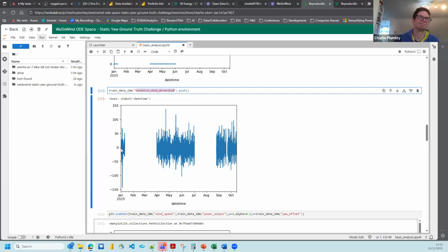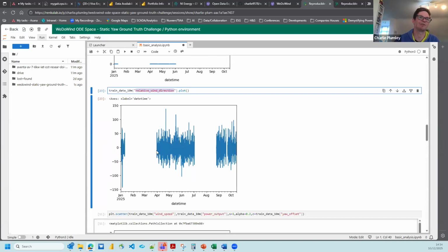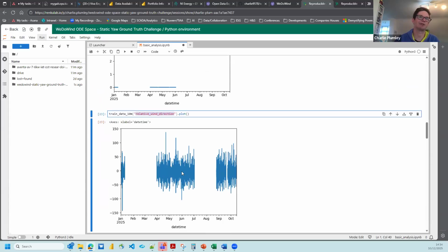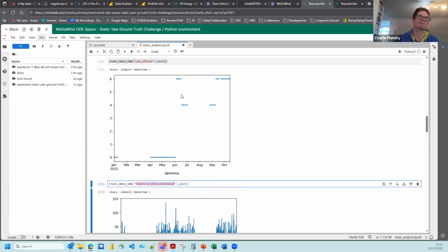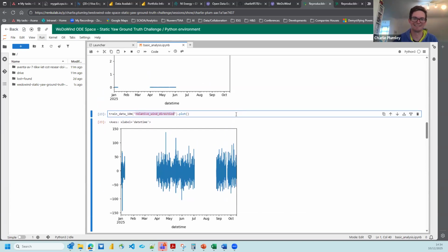If the wind wasn't moving around, then this should be 0 for the bit in January, and 0 for the bit from April to June. It will still read 0 for the other periods here because the sensor is adjusted to still try and point into where it thinks the wind is. So the relative misalignment would still be 0 in this signal. But we know there's an offset, so you're losing generation. Does that make sense? Maybe.